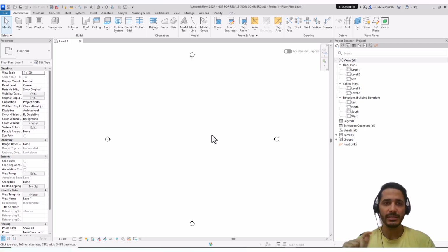We should set the unit because when you enter a number in Revit, for example, when you are going to create a wall, you should input its length. Or if you are creating a level, you should insert its height. This is the importance of unit, because when you are inserting a number, for example, length or area or height or something else, you should know its unit.